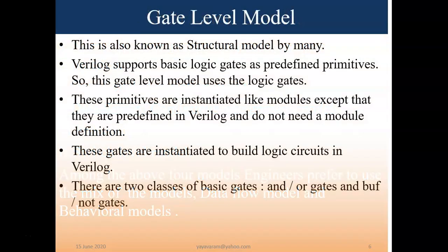Let us start. So, this gate level model, some people also call the structural model. It is popularly known as the structural model also, because Verilog supports basic logic gates as predefined primitives. Predefined primitives means you need not write any program for these gates. They are readily available, like a book available in your library. You can directly call this.